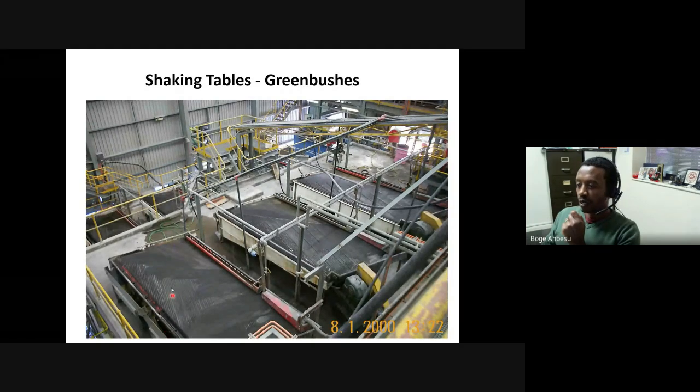So obviously I would want to collect this one. So this is my product. This is my waste. But for the middling, because it contains some amount of valuable, maybe you can decide to recycle it back. So collect the middling, put it back through the table and see if you can further upgrade it. And typically you could use something like that for upgrading. And obviously you could have a number of these tables operating in close proximity with one another.